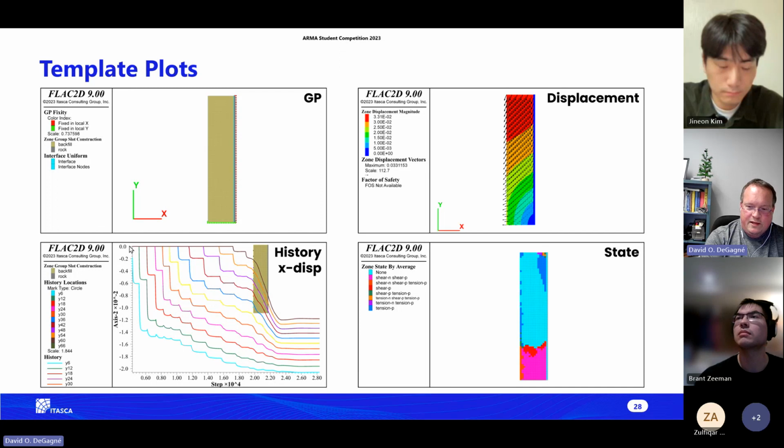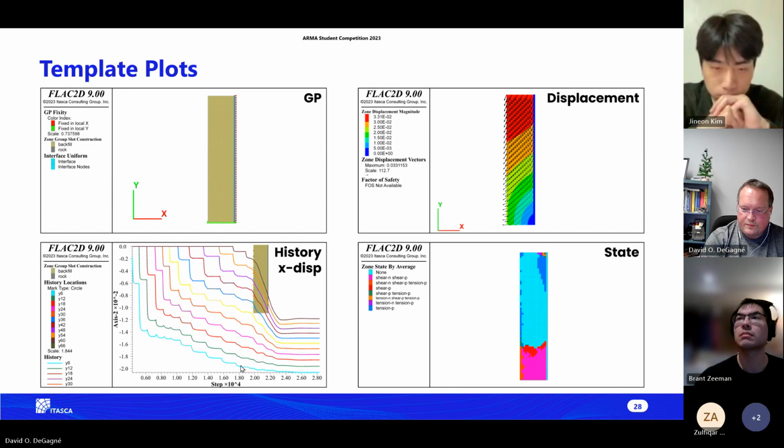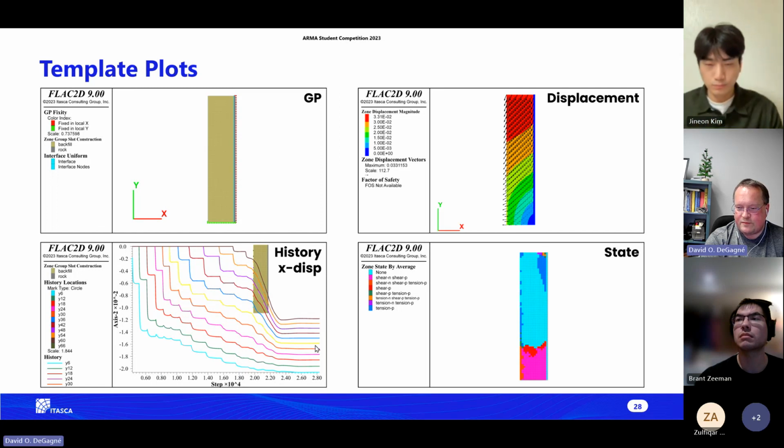And what we're seeing here is, say for this first position, the first cut that we do, we're essentially getting some initial displacement, plateau. The next cut, we have more displacement, but then it plateaus. Then we're getting less displacement, but what we want to see is sort of this stepwise progression. At this point, we're basically up to the top of the model exposed, but you can see here that if we run this out, we can see that they've all come to a nice sort of plateau. So even though we continue to cycle the model, there's no more displacements along this face. And that's ideally what we want to see.